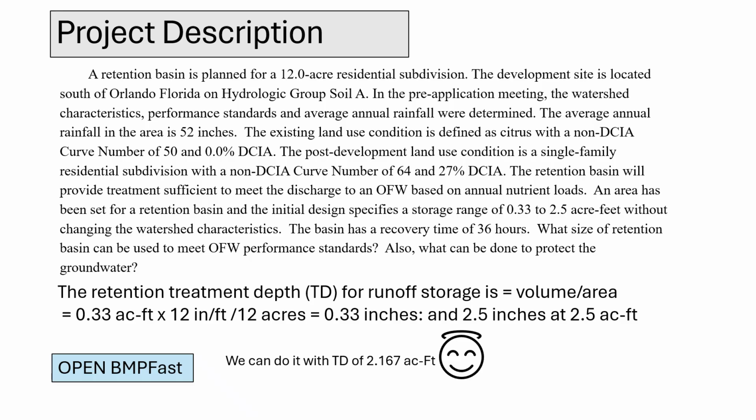The primary objective for this retention basin is to provide treatment sufficient to meet discharge requirements for an outstanding Florida water, or OFW, based on annual nutrient loads. The initial design considers a storage range, giving us two optional retention volumes to assess, 0.33 acre-feet and 2.5 acre-feet.